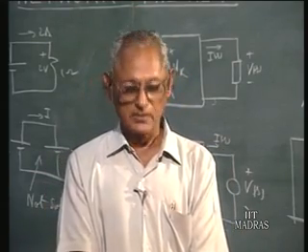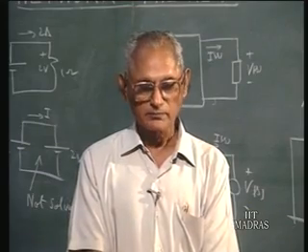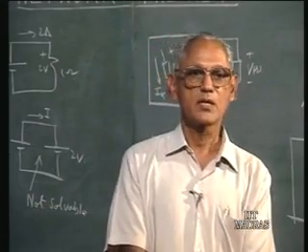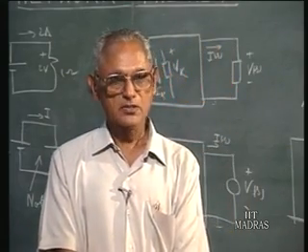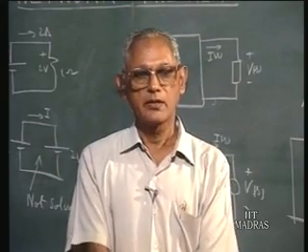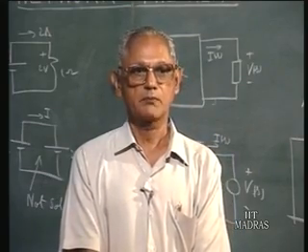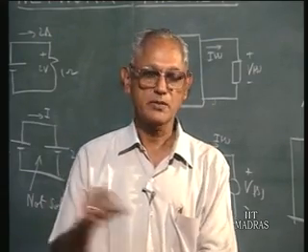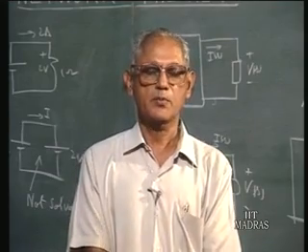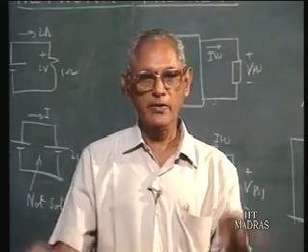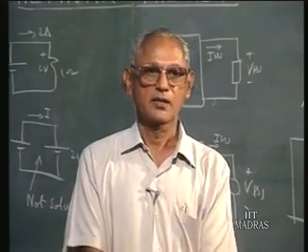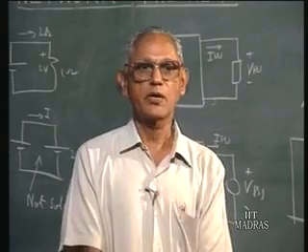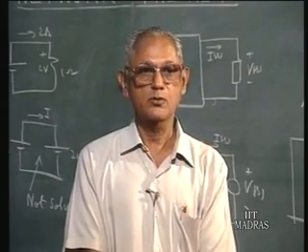We will discuss other network theorems in the next lecture, but before that let me mention that a third network theorem, which is called the Reciprocity Theorem, is something which we had already discussed. I can just reiterate now that in a linear reciprocal network which consists of bilateral elements and reciprocal elements, the ratio of the Laplace transform of the response to the Laplace transform of the excitation is the same when the locations of the response and excitation are interchanged. This is true in a network containing bilateral elements and reciprocal elements. This is something which we already discussed when we were discussing the two-port network characteristics.